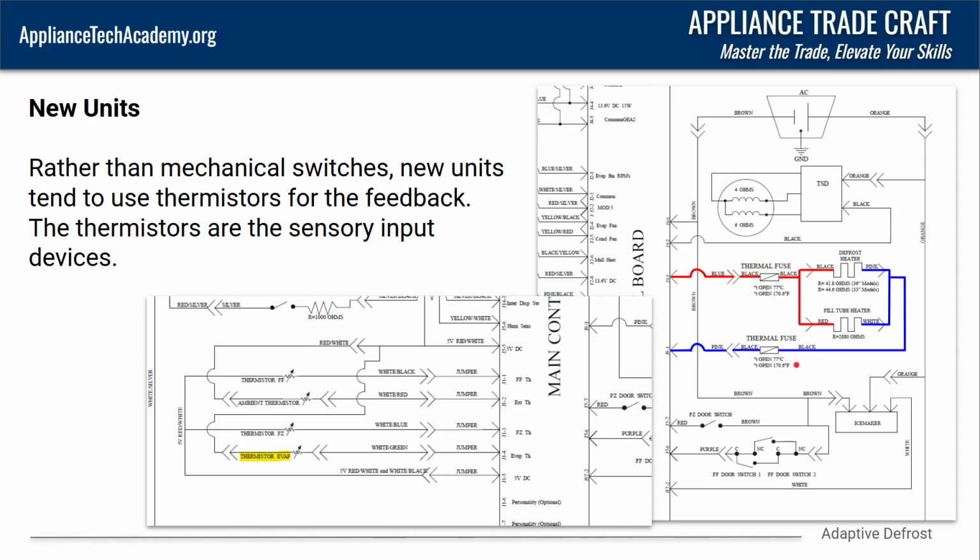Now, one of the things to keep in mind, when you see thermal fuses, they're one-off fuses. They're not going to open and then close. So when you're looking at something like this, there's no mechanical switch in the circuit, so to say, like a bimetal. You just have fuses, and it's called out there, fuse, opens at 77 degrees Celsius or 170 degrees Fahrenheit. So if it gets hotter than 170 degrees, that pops and you're not going to get any heat.